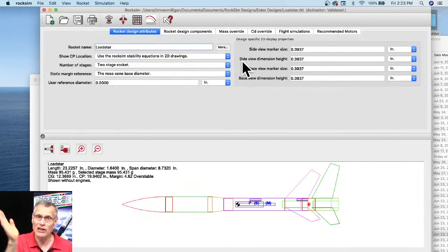it's what path the rocket flies, because the mass is important to how high it goes, but where the mass on the rocket is located is going to determine the moment of inertia of the rocket and how the rocket reacts to wind. If your mass is not in the right spot, you're going to get a different moment of inertia, and the trajectory path could be different. But if there's no wind, it's going to be identical, so then you don't have to worry about it. It's only if you have wind, and what rocket does not fly in the wind?